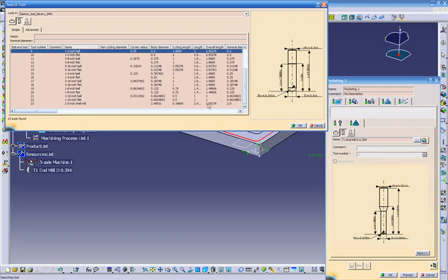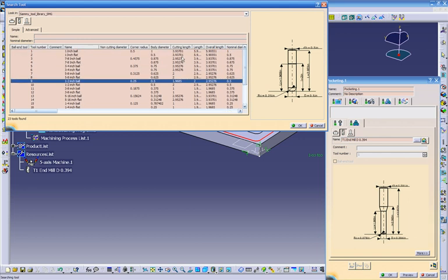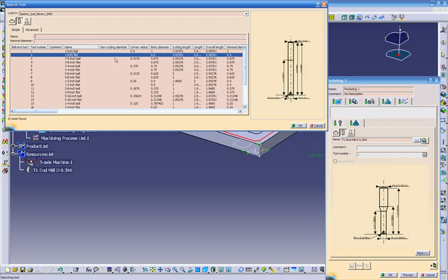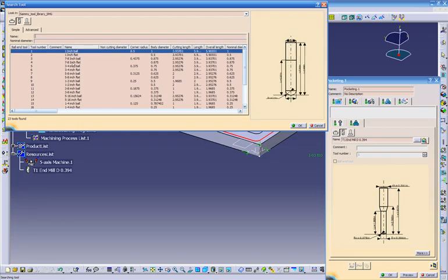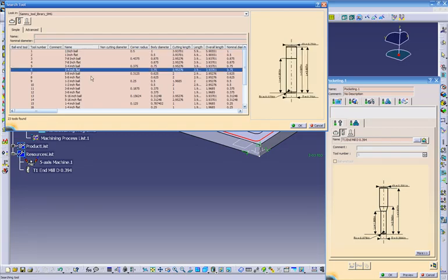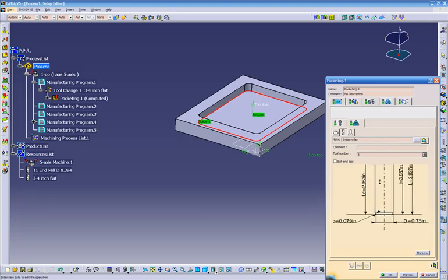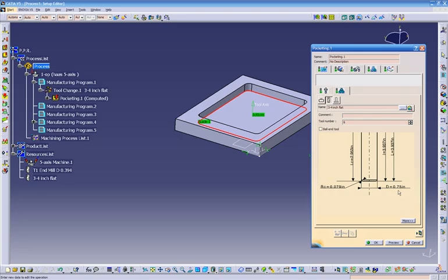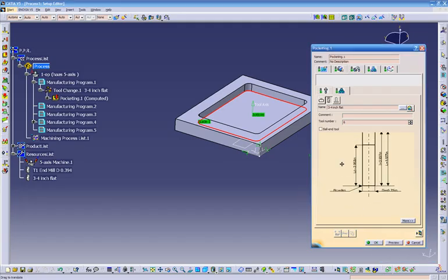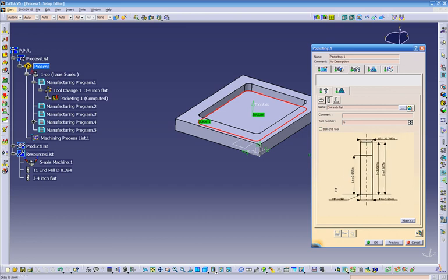This is standard diameters. For example, let's say we want to choose a 1 inch flat. Let's click on 1 inch, 1 inch end mill, 3/4 flat. Click OK. And you can customize it. Even though I said it's a 750, for some reason it puts this radius in here, but you can double click on it and make it 0, make it a sharp corner. And you get your tool over here, customize.